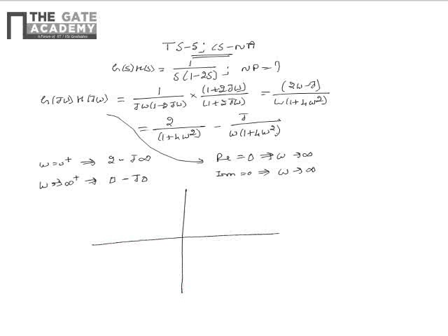From this data, the Nyquist plot of the control system as omega is varied from 0 plus to infinity plus can be plotted as shown. Now due to the symmetry, as omega is varied from infinity minus to 0 minus, the Nyquist plot can be obtained as shown.